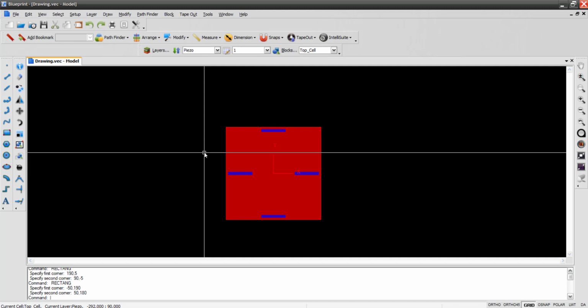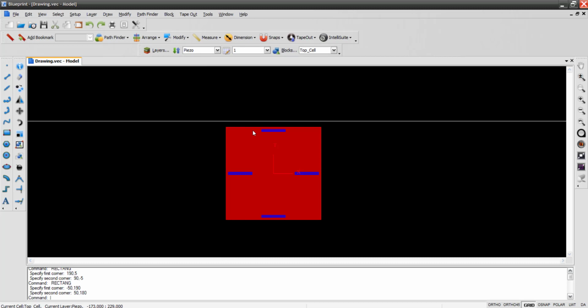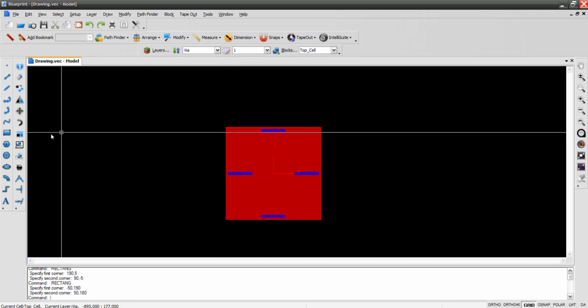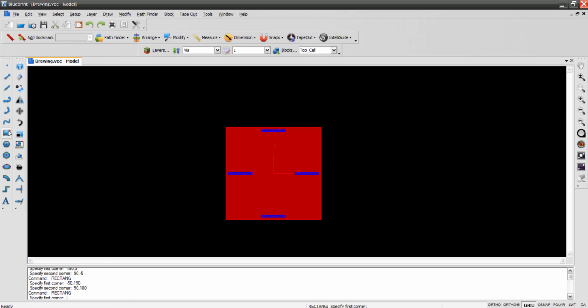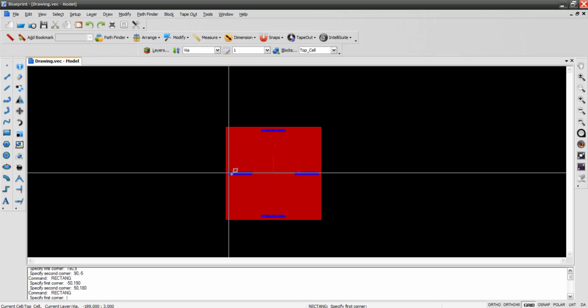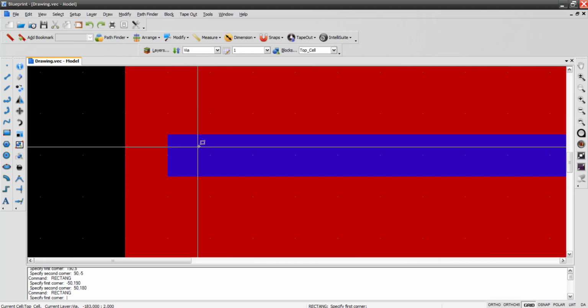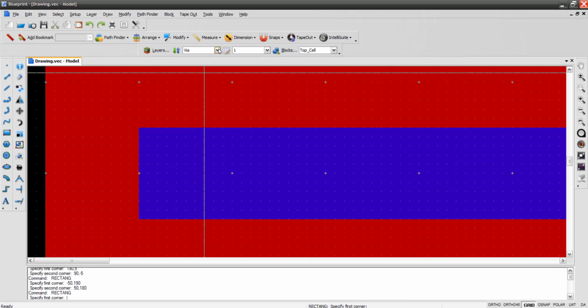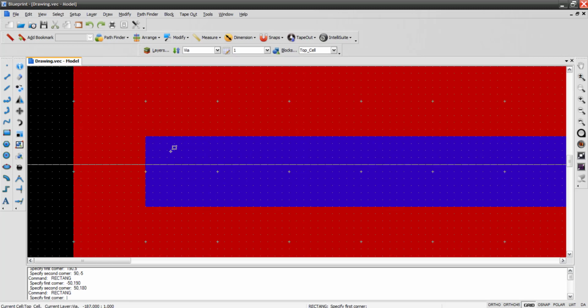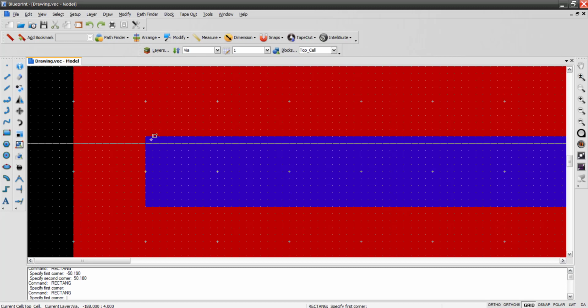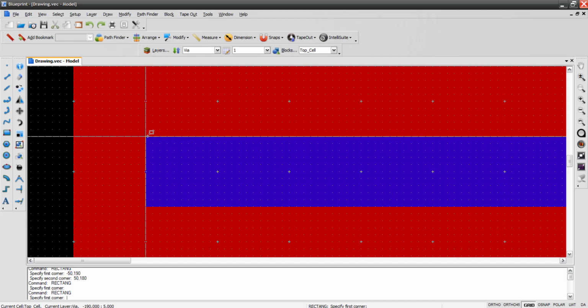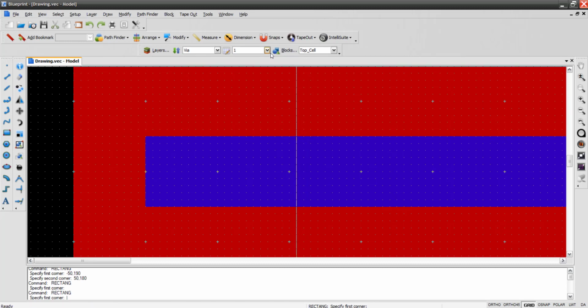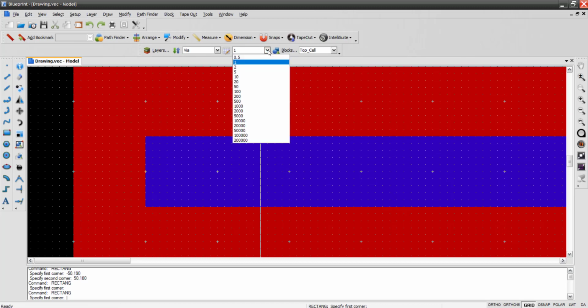Then let's create via hole buttons. We go to via, then here let's create a via contact and 4 different piezo resistors. So here we select the via. So I'll go to one of the piezo resistors and then select a rectangle. I can also draw a rectangle in this fashion. So here each dot what you see is of distance 1 micrometer by 1 micrometer.